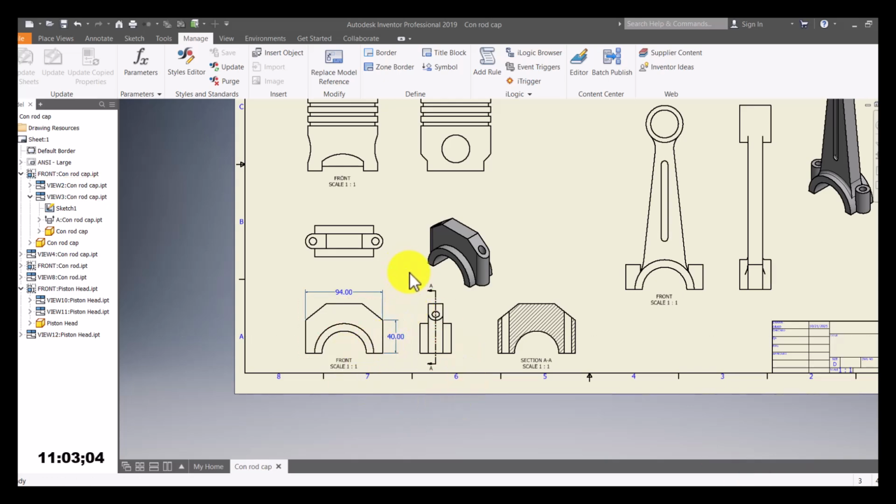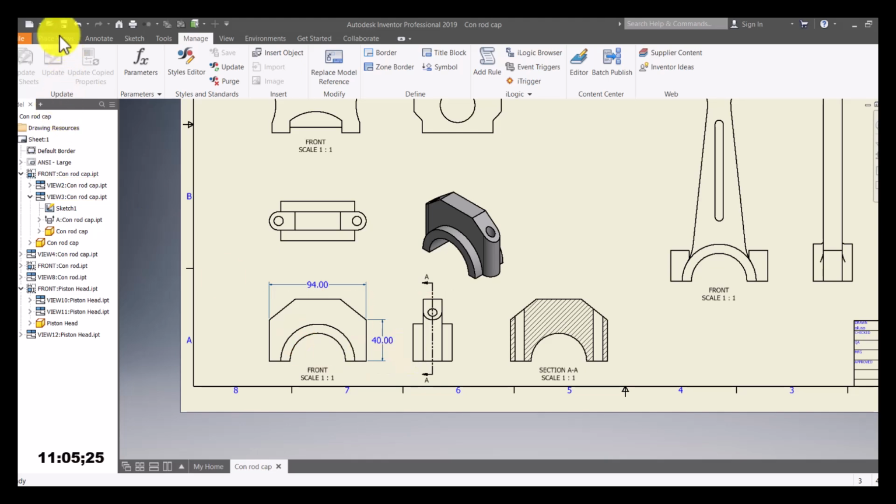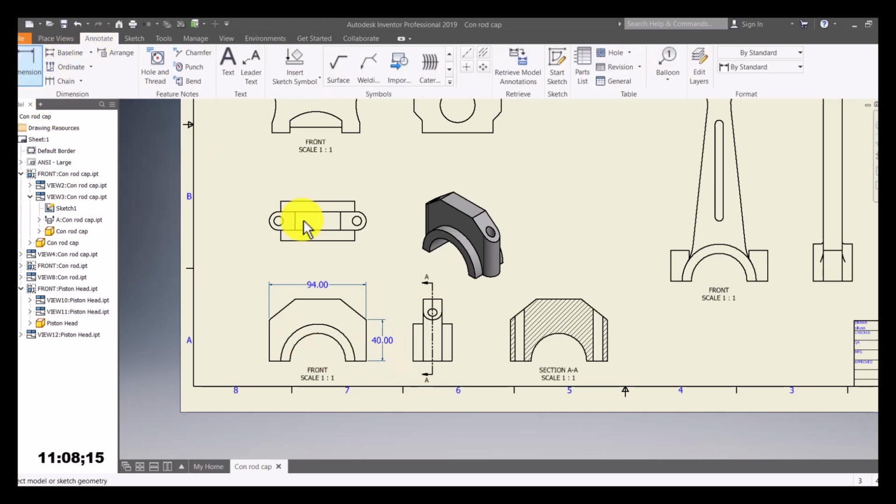All right, so now with this well done, I can bring in all that dimension. So I'll go back to my annotate dimension and bring in all that dimension depending on what I need. So I can easily dimension all the parts of my drawing now that I have the right setting. So from center to center, I can have the dimension.